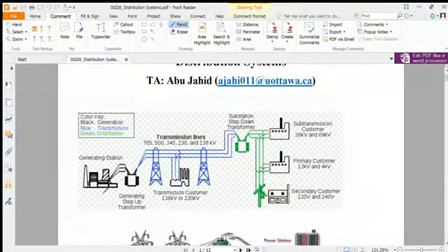So here's a generation station. A couple of synchronous generators can be connected in parallel in the power station, and the generating voltage is typically lower than the transmission voltage. Generation voltage could be 11 kilovolt to 13 kilovolt. Sorry, it's 30 kilovolt. And then a step-up three-phase power transformer is used to convert to the high voltage transmission line. It is actually an AC to AC converter.